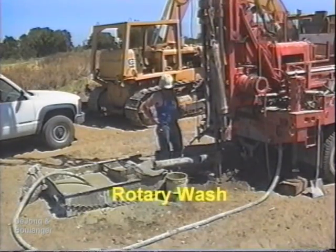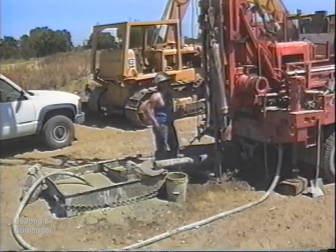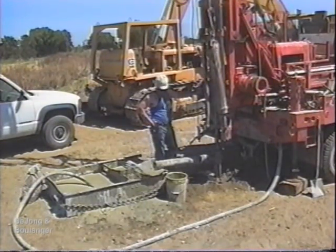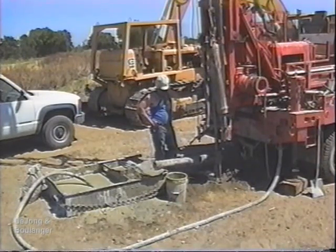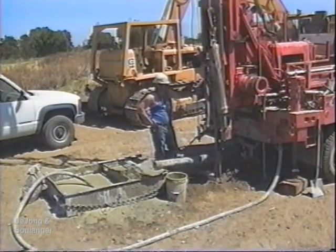Mud rotary, or rotary wash drilling, is very different from the continuous flight auger methods. The underlying principle is that mud, a mixture of water and bentonite, circulates through the borehole, bringing the soil cuttings to the surface and supporting the sides of the borehole.